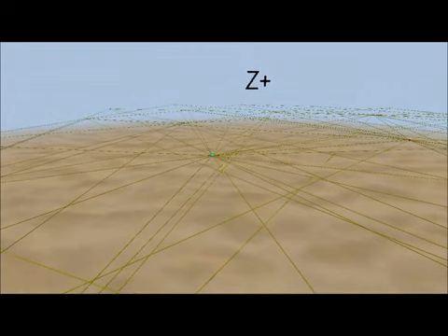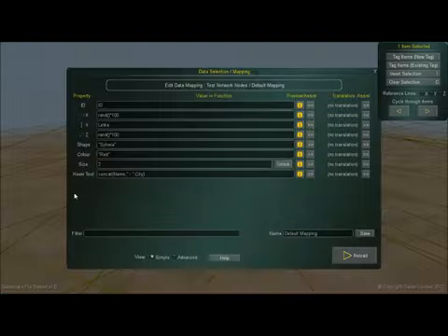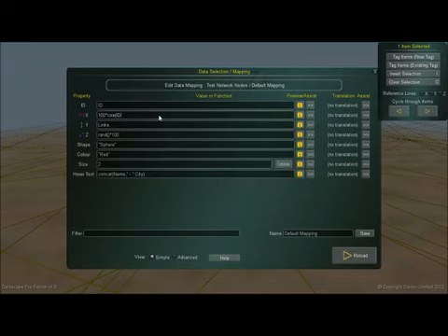What we'll do now is try a different starting layout, because the starting layout can have quite a big impact on how you view the data. So we're going to go back to the nodes and back to the data mapping. This time, instead of using the random function, we're going to deploy the various points into a circle. So we give it the radius of the circle. We're going to use cosine for this one. The angle is going to be the ID number divided by the total number of points we have. We've got a total of 28 points, so that's 1 divided by 28. That'll give us fractions of a circle. So we need to times that up by pi,